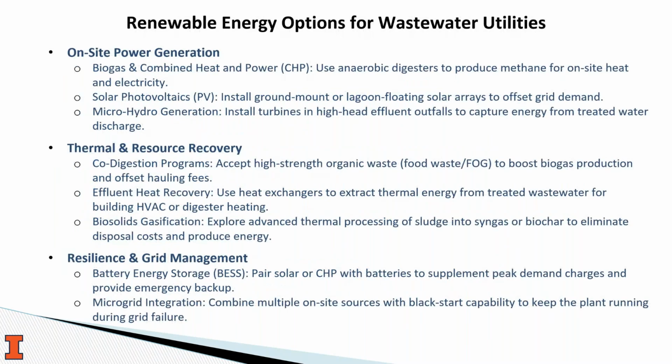And very quickly, there are renewable energy options out there for wastewater utilities as well. This might be more relevant for bigger systems than smaller systems, since these kinds of upgrades do require higher upfront costs. But I just want to quickly highlight some of those renewable energy opportunities. Generating on-site electricity and recovering heat from the digester building, using combined heat and power systems to do that, is a highly energy efficient upgrade that utilities can implement.